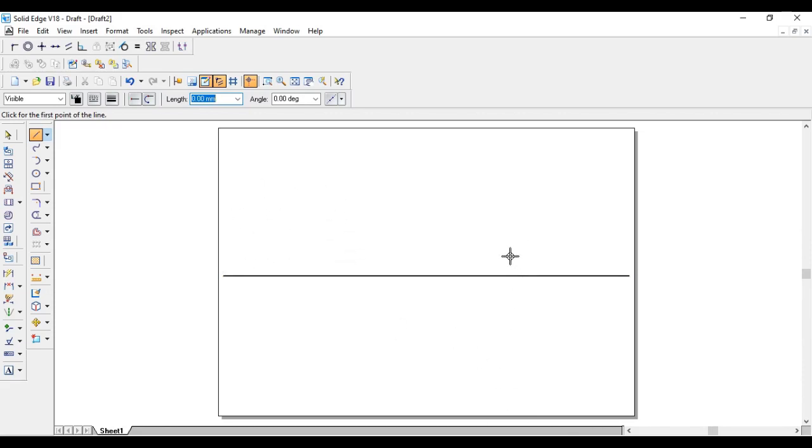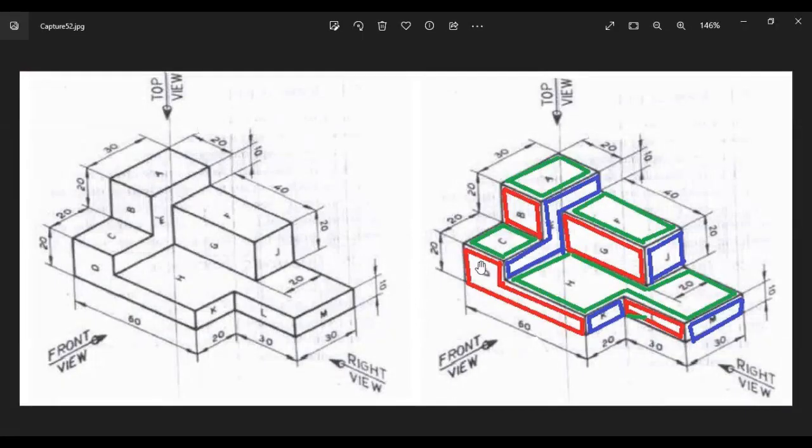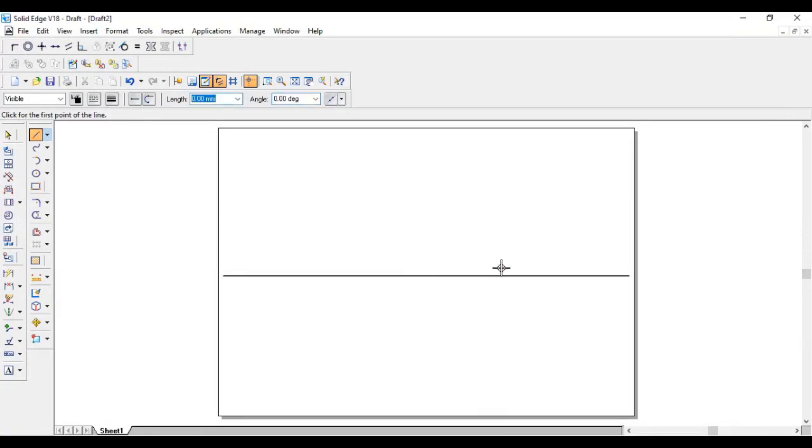I will start drawing this side by looking at this one, as I told. The red lined mark indicates the front view. We'll start drawing this side. When we look at the image carefully, this dimension will be 20, then this dimension is 60, then again this gap is 10, this gap is 40, and this gap is 10 again, and you can just join this.